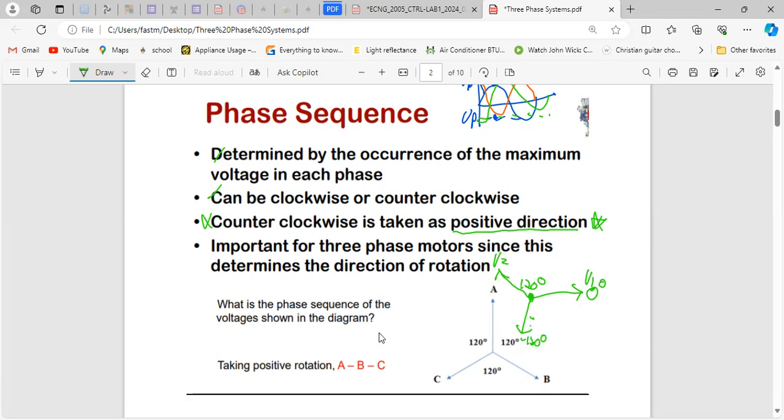They are 120 degrees away from each other, but depending on what direction you're going in, and you'll see this more when you try the phasor, if you go from the reference to V2, it'll be 120 degrees. But from the reference, if you go to what they call V3, it'll be minus 120 degrees.